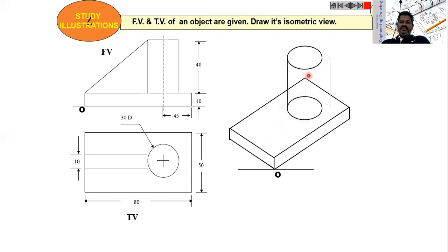After constructing the cylinder, with the usual procedure, as you're aware, with the given diameter, construct a rhombus on the plate and construct one more rhombus at a height of 40, then construct the ellipse here and construct one more ellipse on the surface of this plate, join the tangents of the ellipse like this.